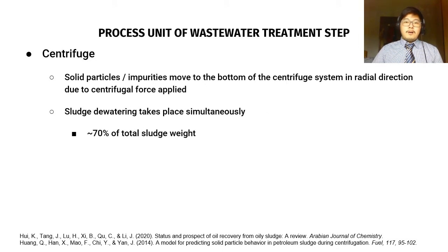According to the principle of settlement via centrifugation, the applied centrifugation force onto the oily sludge will cause the solid particles or impurities to move towards the bottom of the centrifuge system in the radial direction. In addition, centrifugation also allows for sludge dewatering to take place, where water is retrieved from the solid particles or impurities, which can be in large amounts, as much as 70% of the total weight of the sludge.